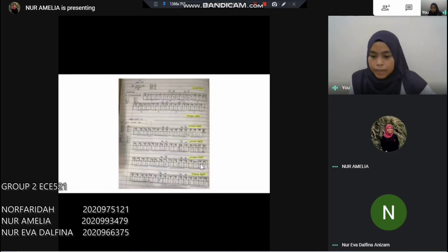And then next, we will have GPIO IDR. Firstly, we will have a masking, which is a value of 0x00000012. And then when switch 1 is pressed, we will have a value of 0x00000010. While when switch 2 is pressed, we will have a value of 0x00000002. For GPIOB ODR, which is the LED, when switch 1 is pressed, we will have two conditions, on and off.